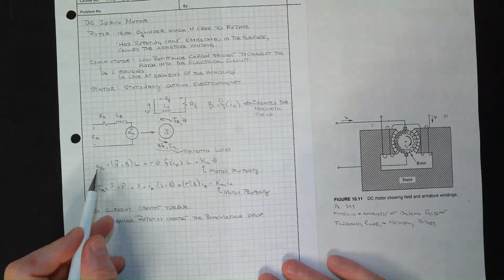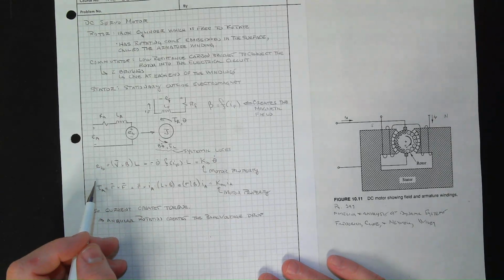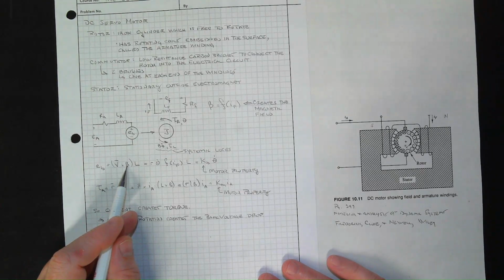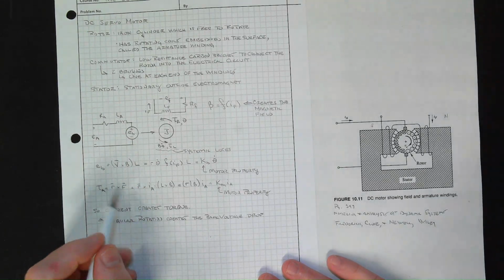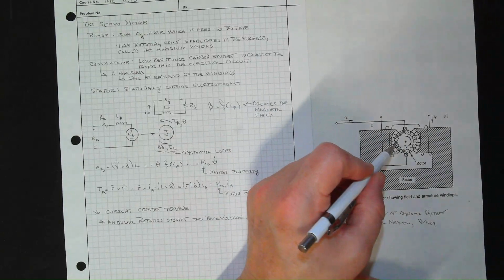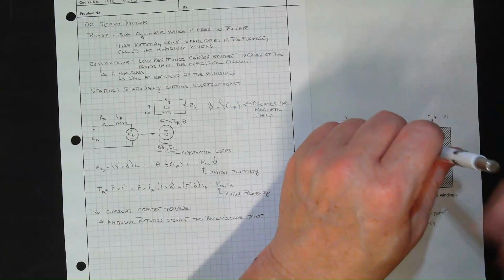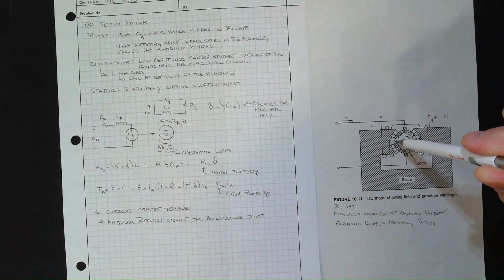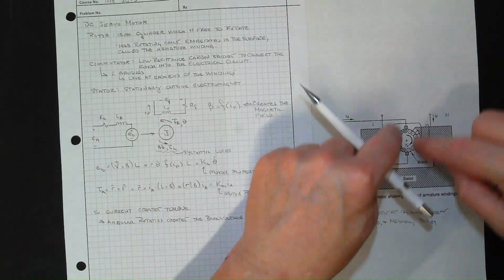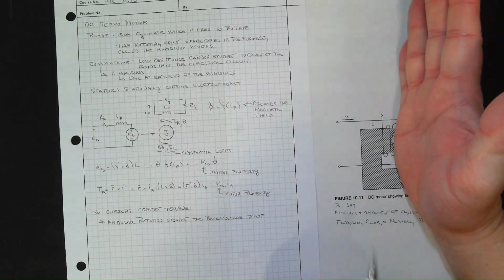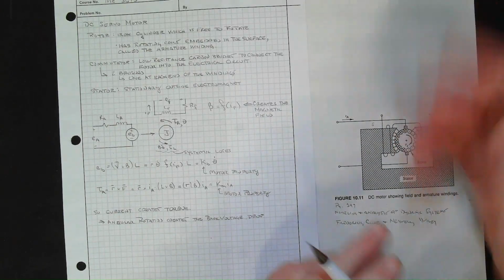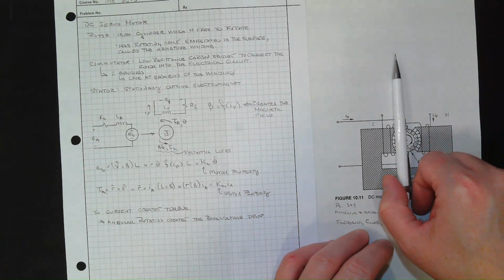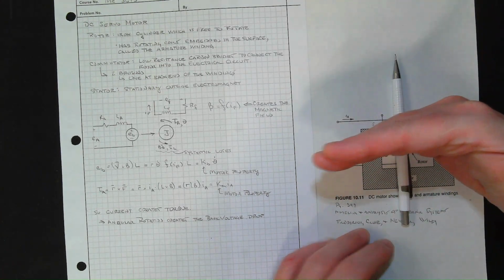All right, back voltage. Back voltage is velocity cross magnetic field times L. Let's look at this conductor. This is going in, notice my pencil going in. That's where the current's going. But this thing is rotating this way, so the velocity is going up. Here's the velocity going this way, with the magnetic field going that way.